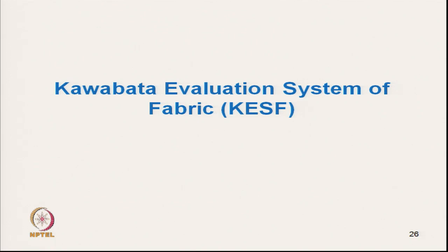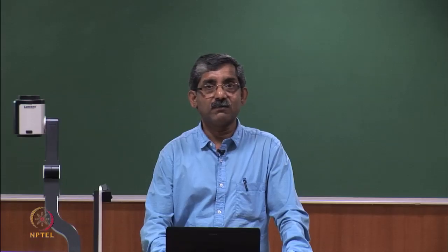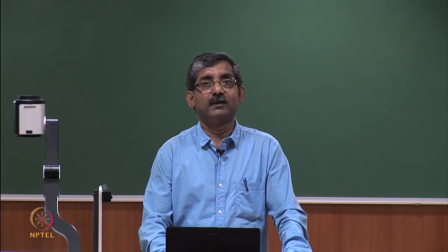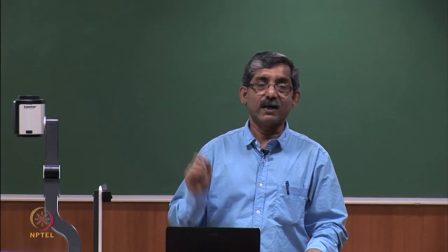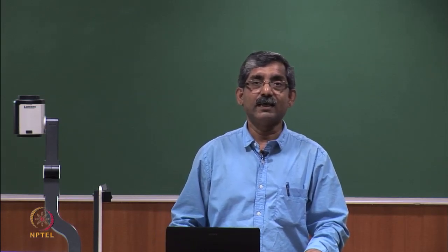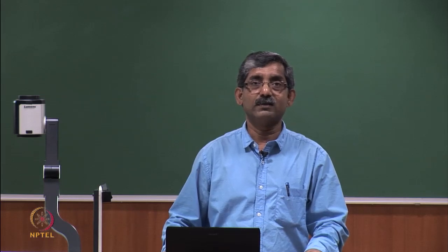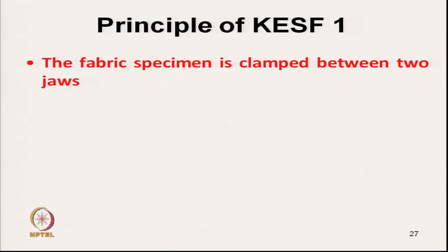So, first we will start with the Kawabata evaluation system of fabric, the KESF system. We start with the first module, KESF 1, which measures 2 characteristics, tensile characteristics and shear characteristics.